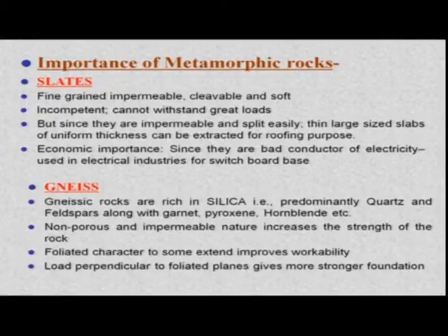Load perpendicular to the foliation: foliated planes give more strength, or a stronger foundation. So this is one advantage of this one. Load perpendicular to the foliations gives a stronger foundation, but if the foliations are inclined, or if the load is inclined, then you will have problems.